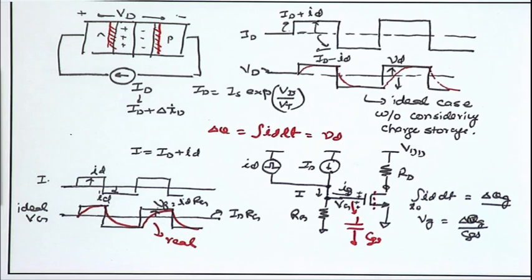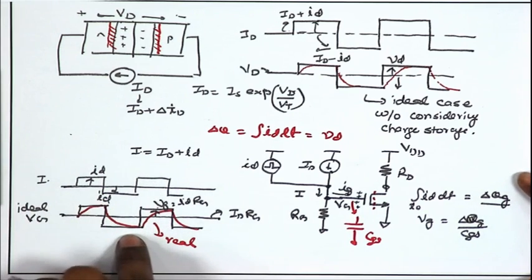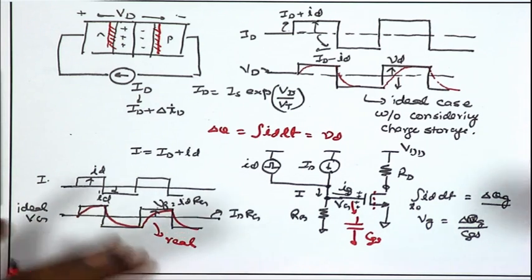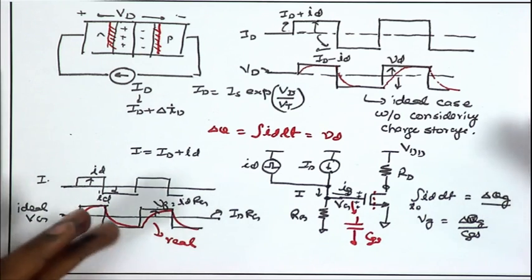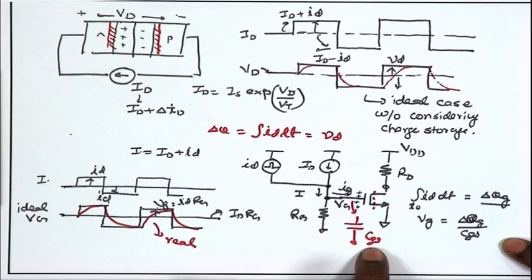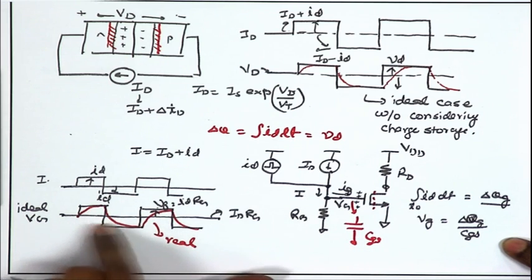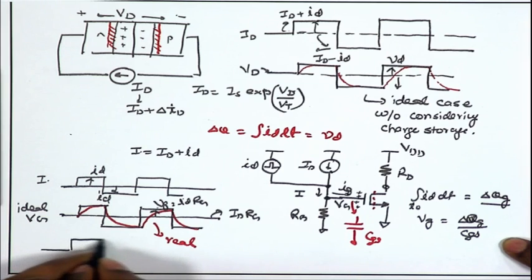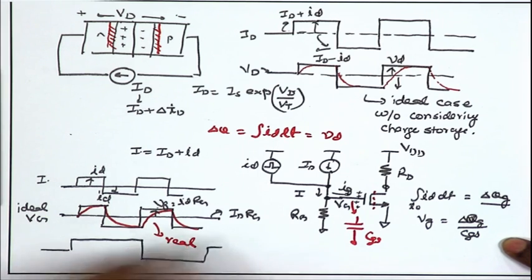That is the basic effect that these parasitic capacitances produce. They are slowing down the circuit response, and as a result your overall circuit performance, speed, and bandwidth is going to suffer. Therefore, we call them parasitic capacitances. Their importance becomes more significant at higher frequencies, because at lower frequency the period of the signal is much larger, and as compared to the period, the signal will be able to rise much more quickly. So, we can ignore this finite rise and fall time.